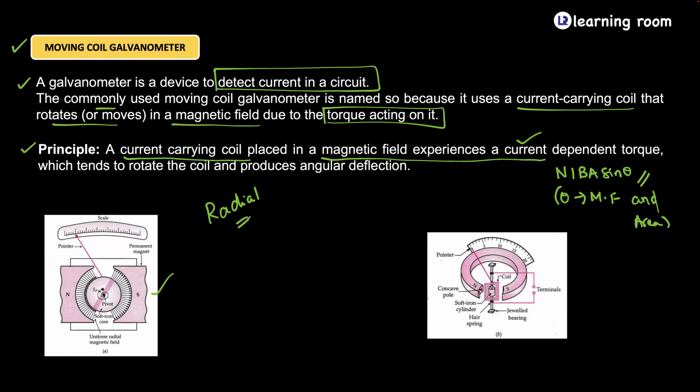So my question is one thing. When you saw the activity, when I connected the positive terminal here and the negative here, the pointer went to the extreme, right? It went till here. But when I cut the connection immediately, what happened? The pointer came back to its original position. Can I say that there is some restoring force that is existing? I don't know what that restoring force or restoring energy is, but there is something that is helping the pointer to get restored to its original position. So who is doing it? The spring.